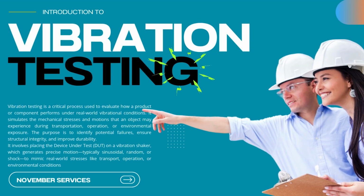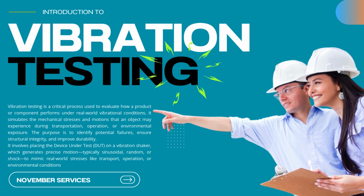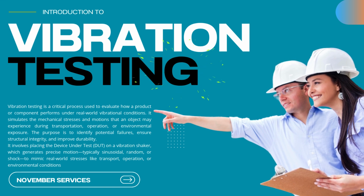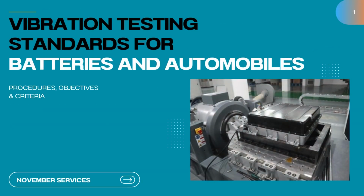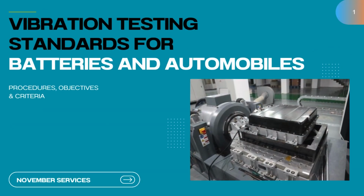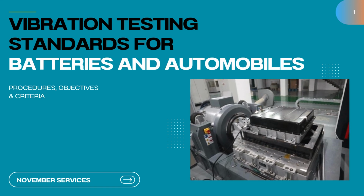Vibration testing is a critical process used to evaluate how a product or component performs under real-world vibrational conditions. It simulates the mechanical stresses and motions that an object may experience during transportation, operation, or environmental exposure. The purpose is to identify potential failures, ensure structural integrity, and improve durability.